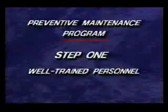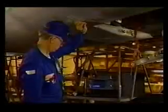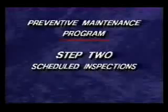The first and perhaps most important requirement of any aircraft corrosion preventive maintenance program is to have mechanics who are well trained in the essentials of corrosion control. A well-trained mechanic is the best and most cost-effective defense against corrosion. The second step of the program is the establishment of regularly scheduled inspections. All the aircraft corrosion training in the world is ineffective without daily, routine, or special corrosion inspections.